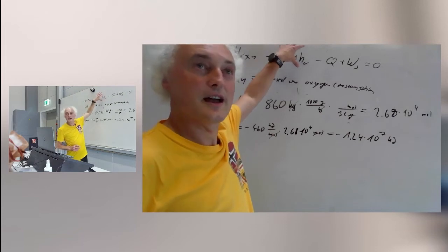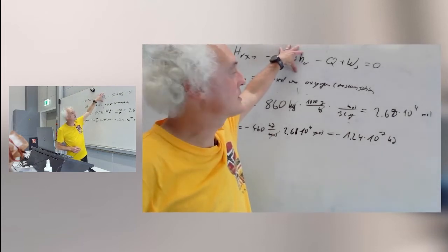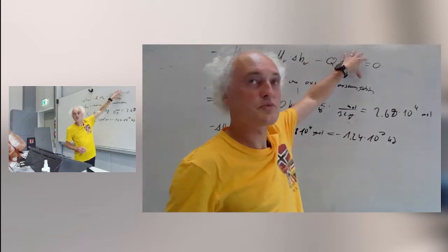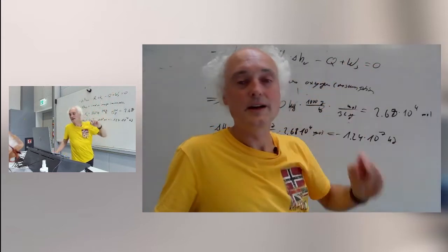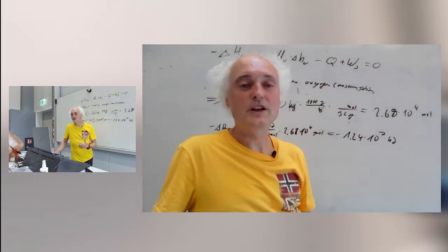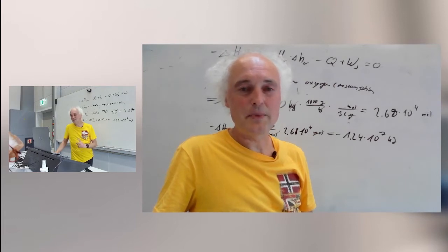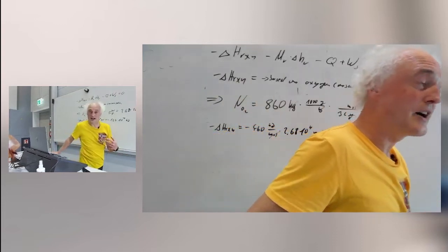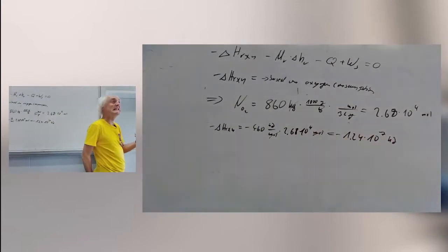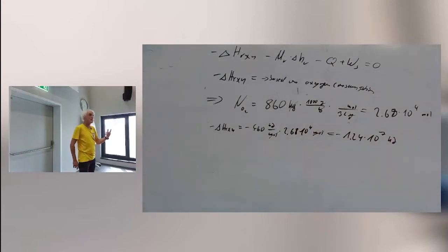We have talked about how to calculate this, and of course with the stirrer power you go in. Don't forget the power input is 50 kilowatts. So you need to take into account that this runs for 2 days. This is a power.